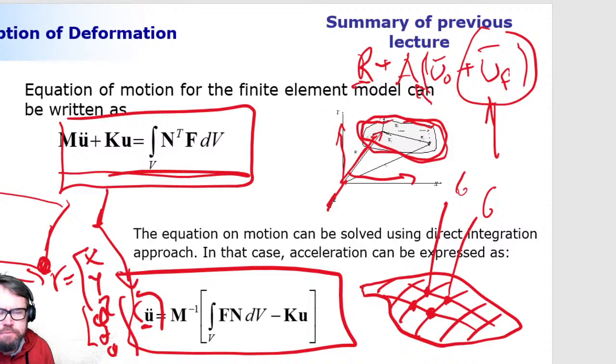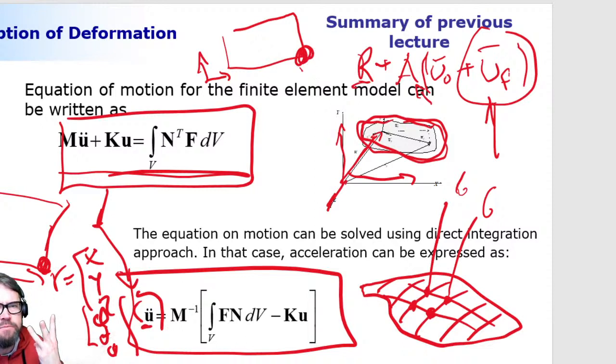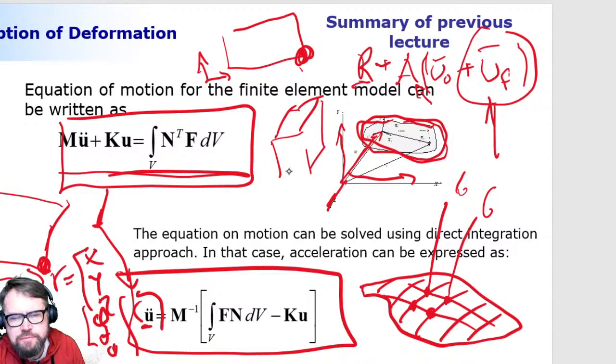Oh no, a better idea would be to draw this plate element here. Here's a plate element, here's a reference coordinate system. So one node here consists of 6 degrees of freedom that are 3 displacements, 3 translations if you may, and 3 rotations. This is a very typical scenario. Then the solid element, which is like a cube, looking like this.